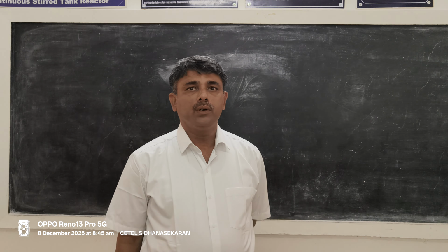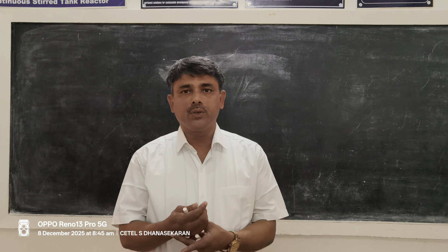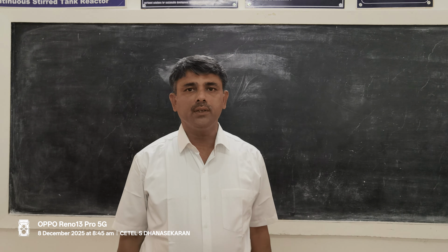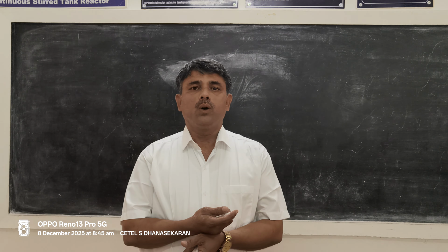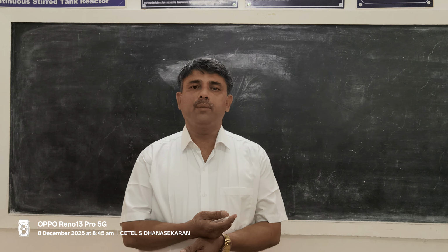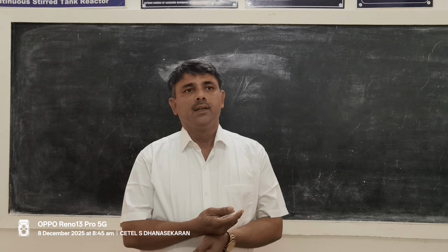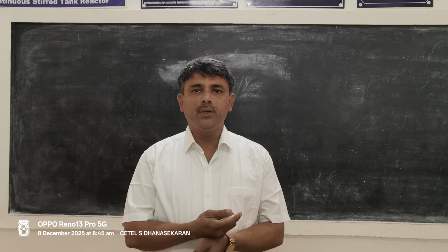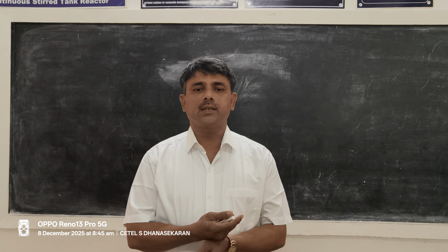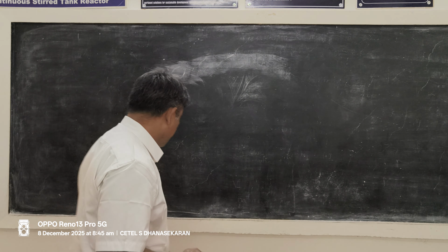Today, I am going to discuss molecular diffusion, steady state molecular diffusion in fluids, one at rest and one under laminar flow. For both conditions, I am going to derive the flux equation. This is the first stepping stone to enter into the mass transfer ocean. Clear?